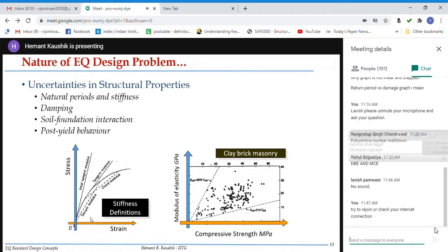Now, do you think that there is no error here? The error is huge, and you will be surprised to know that in the majority of cases, the errors are more than 50-60%. But we are still comfortable because we know that in all regions across the country, everybody is using that same equation, right? So if I say that this is M25 grade concrete, people across the entire country will say that the modulus of elasticity is 25,000 MPa. That gives us some confidence. The uncertainty issue can be handled separately by having some factor of safety. That is what codes do.